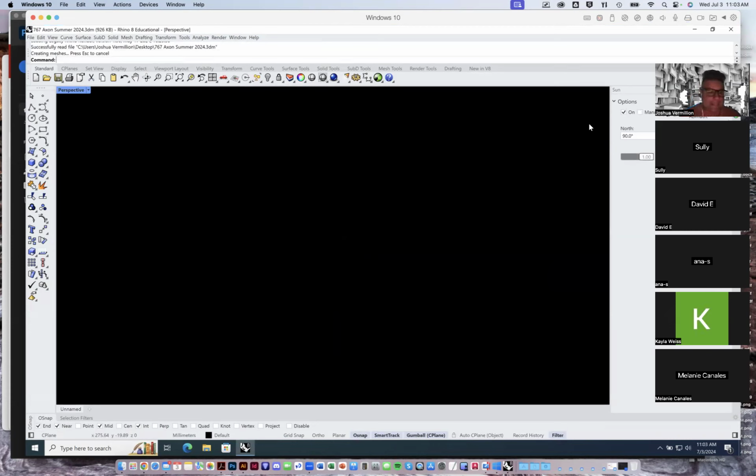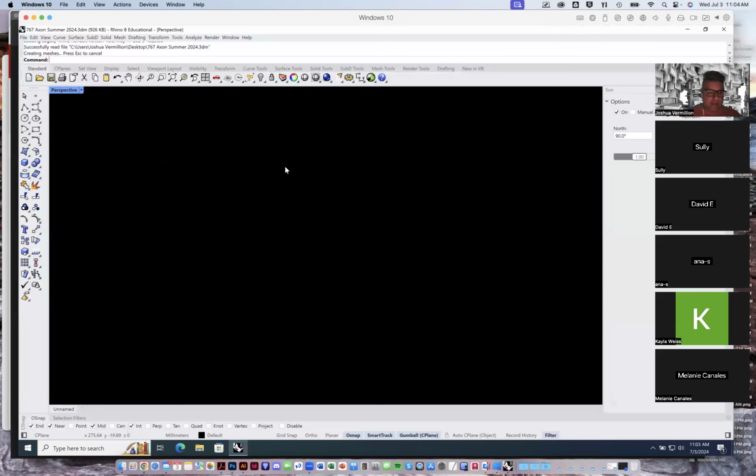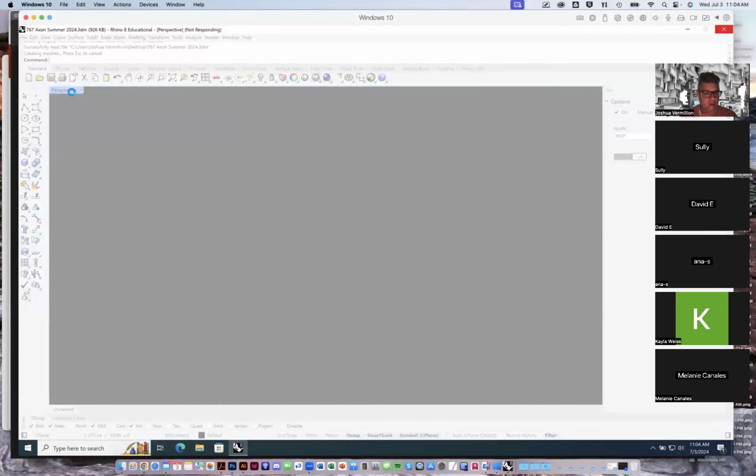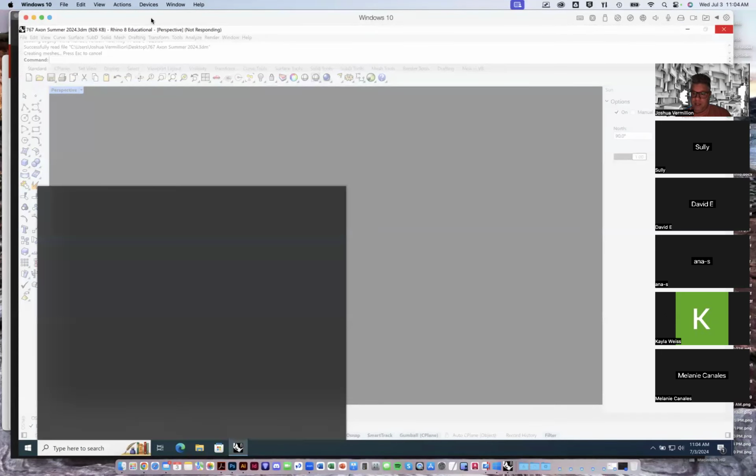All right. So a couple of things here to remember again. These are details that aren't necessarily obvious. We talked about clipping planes. Let's see here, what do we have going? Come on, Rhino, load up. Just waiting on it. But we're going to do a couple of things here. One is I'll just redo a clipping plane. I'll position it, make sure it's flipped the right direction, and apply it to the right view. And then from there, we'll turn on sun and shadows.